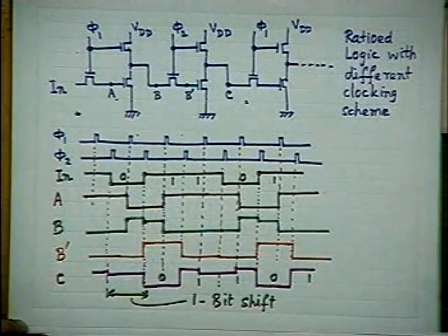And that has resulted in this kind of kink. I am sure that you will appreciate that these kinks are not desirable. How do we reduce these kinks, these sudden depressions? How to reduce these kinks? Yes, please. By reducing the clock duration. Again, if you reduce the clock duration, then there is the problem of full charging. The clock duration should be such that the charging is full. That is very important.